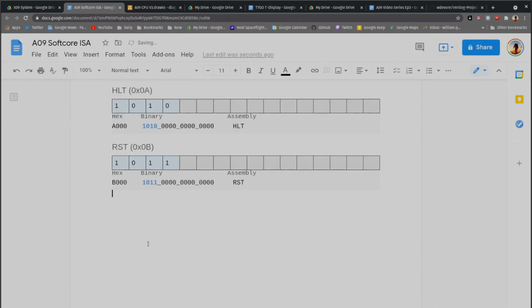The reset instruction is the last of our actual instructions, and again, it is another inherent instruction, meaning the code specifies exactly what the processor needs to do. We need nothing else following it in any of the other bits. In this case, it will immediately stop whatever the processor is doing and send it back into the reset sequence. And that's what this instruction does. The only other way to cause a reset is to trigger the reset pin, to say, for example, bring yourself out of the halt condition.